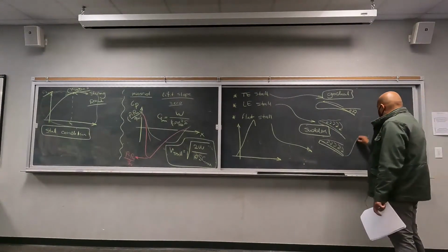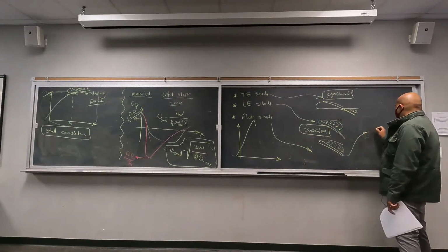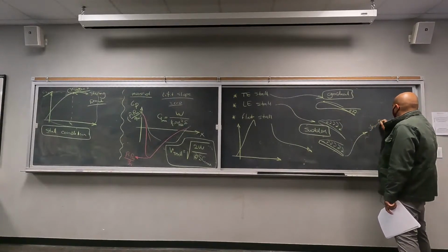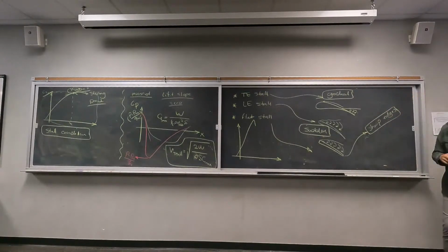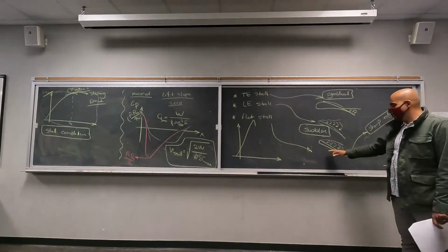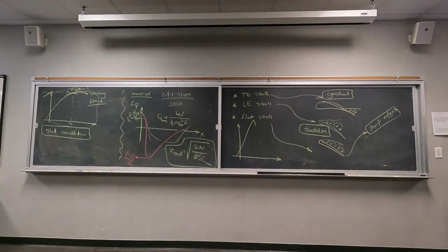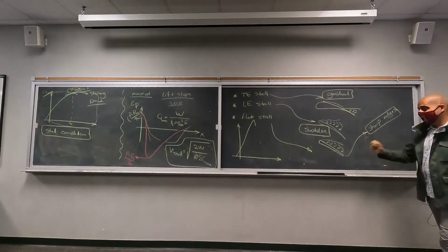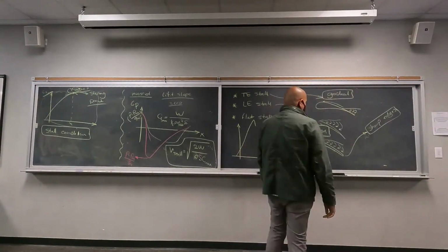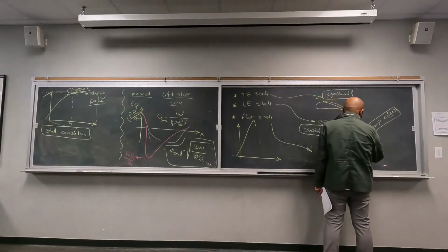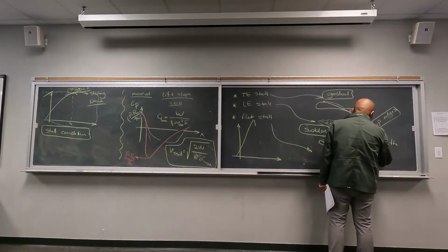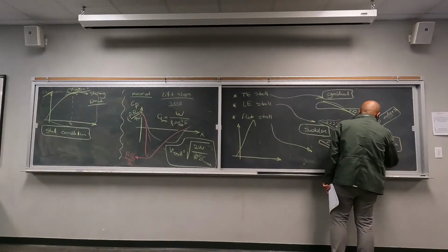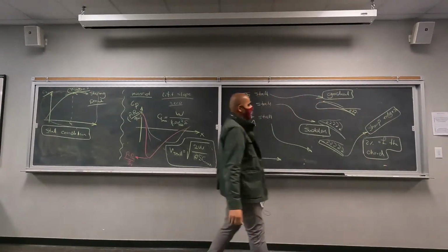The reason they stall earlier is because of very sharp edges. Again, your flow sees a flat plate with sharp corners, right? It doesn't mean that this flat plate has to be a sharp flat plate, but it's so thin that your flow sees very sharp corners. And we actually have a definition: your thickness has to be 2% of the chord for your airfoil to be considered a flat plate.